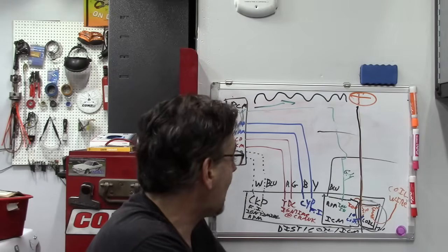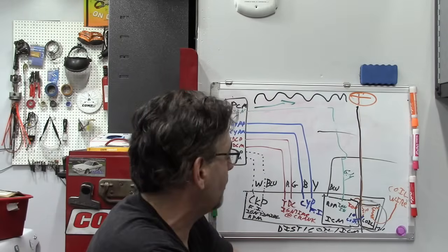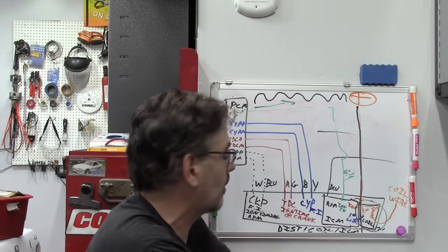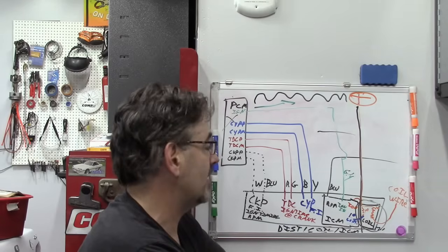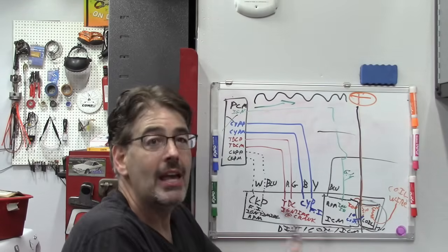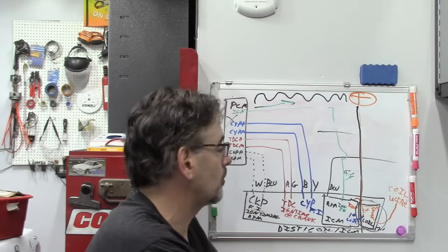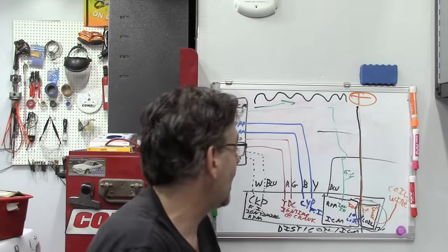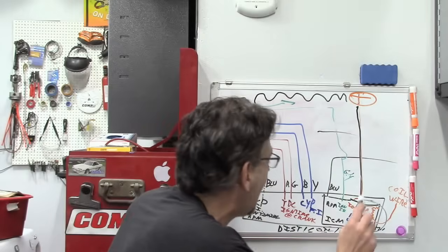If we cannot, giving the coil a ground and giving it an input, if I do that and this coil doesn't fire, we are done. We are putting a coil in this car, and that is all. Now the only question is, can you do that? Can you put a coil into the distributor, or is the distributor non-serviceable and we have to replace the whole thing anyway? That I don't know, but I don't care, because I want to find out exactly what the problem is here.